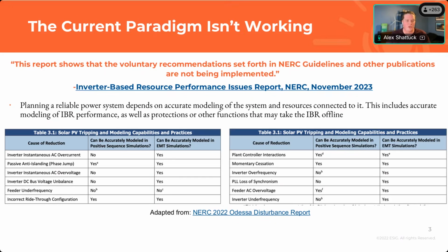The only one that is a no for the EMT is feeder under frequency. And the reason for that is that there just aren't, in the phasor domain or the EMT domain, those types of models available from the manufacturers of those feeder type relays. There are lots of reasons for that. The main reason is that it's just really hard to get those to work right, and it's very hard to model them in that space. And the major manufacturers, which account for most all of those relays and protection functions, aren't making those models. So they're just not available, and that's why there's a no there.